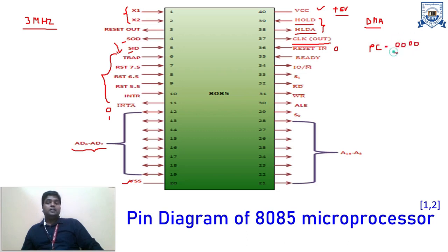Okay, as we know that the content is basically represented in hexadecimal representation. So this is your 16 bits information in hexadecimal format, that is represented by these 4 zeros. So the program counter content will become 0. That means this 8085 has been reset.